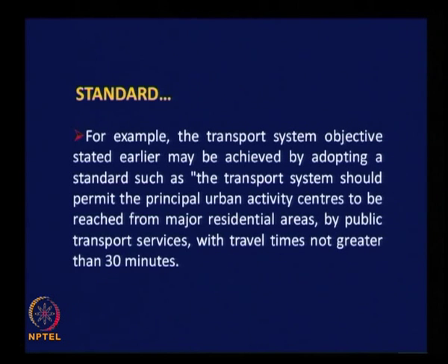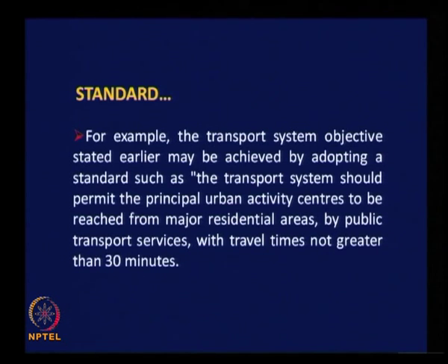Adopting a standard such as: the transport system should permit the principal urban activity centers to be reached from major residential areas by public transport services with travel times not greater than 30 minutes. There is some quantitative aspect, right. This is what we mean by accessibility to job opportunities and other activities to all sections of the society by providing good public transport service. Now we introduce a quantitative term indicating that the travel time should not be more than 30 minutes to reach any major activity center in a particular city or town. There is no sanctity about the number 30, it depends upon the city you are handling. It could be 40 or 50 or sometimes 22,